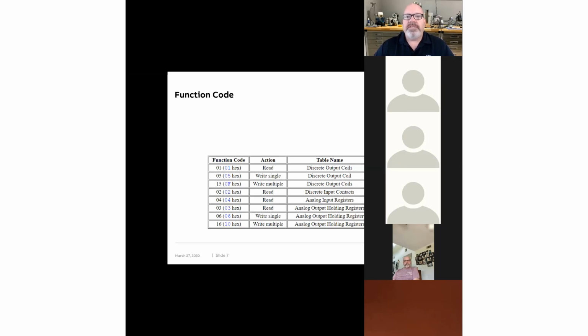When I do that request, I can't say, well, skip register 2 and 3 and just give me 1 and 4. I have to take back the whole sequence when I ask for multiple registers. Now, if I want just register 1 and 4, I can poll register 1 and register 4, but that's 2 separate polls, which means I have to ask for the data, wait to receive it back, and then ask for it again, and then hopefully receive it back. So it takes more time than reading a whole list.